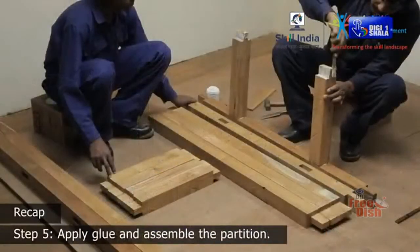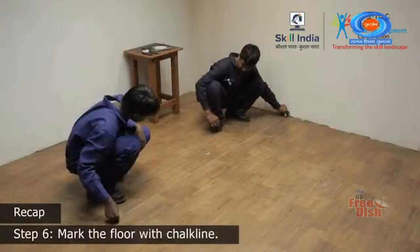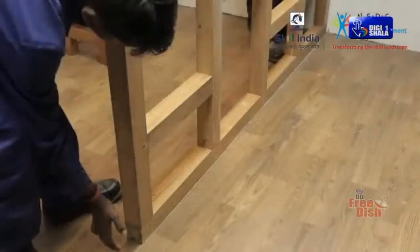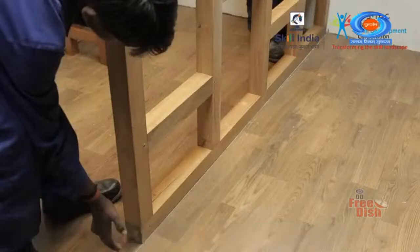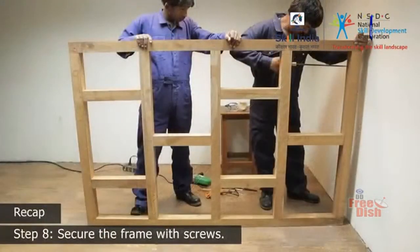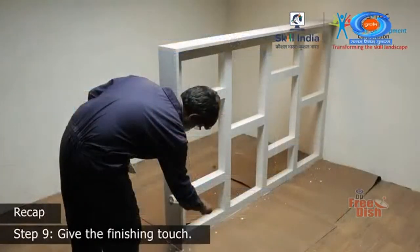Step 5. Apply glue and assemble the partition. Step 6. Mark the floor with chalk line. Step 7. Position the frame on the floor and align it to the wall. Step 8. Secure the frame with screws. Step 9. Give finishing touches.